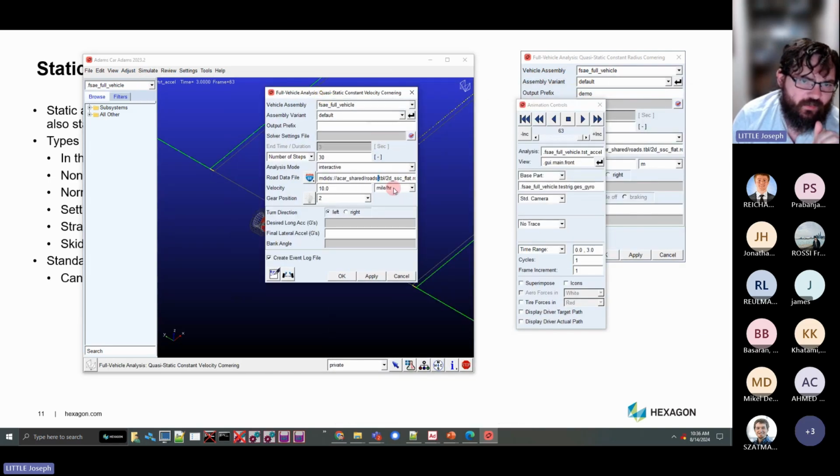When I say quasi-static simulation, I'm usually referring to the simulation that happens before an event, but there is a dedicated standalone quasi-static event, and this can be useful to sweep quasi-static parameters and see how the vehicle responds, and to help you understand quasi-statics. But just know that when most people talk about quasi-statics, it's the thing that happens before a different maneuver. But I will run this quasi-static cornering real quick.